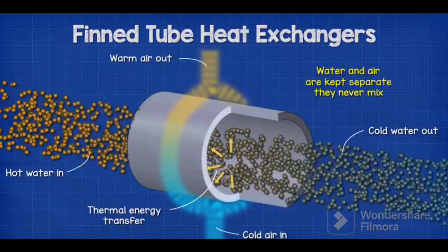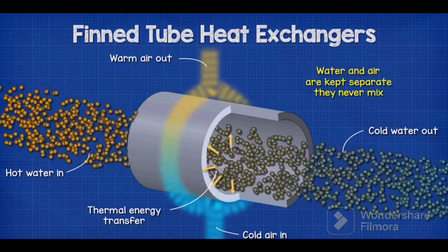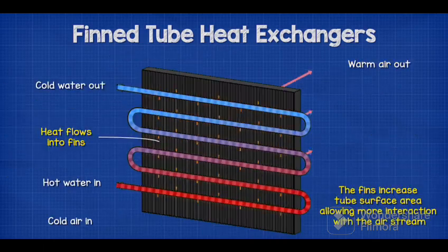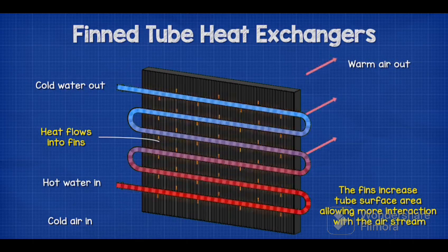The heat passes from the hot water through the tube wall and into the air. The heat of the water travels out through the pipe wall and into the fins. The fins increase the surface area and allow more interaction with the airstream, which improves the heat transfer.